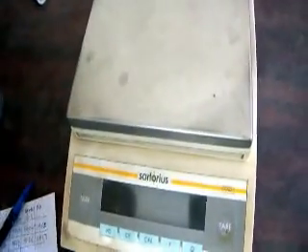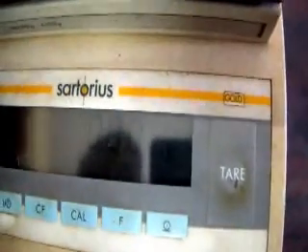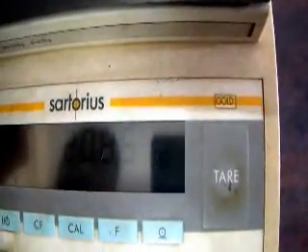Now this is the third, for the 30 centimeter soil sample, and this is 00. So this is 20.85 gram. So this is the gravimetric sampling method. We need to take the weight of wet soil plus box, weight of dry soil plus box, and weight of the soil sample box to find out the soil moisture in terms of volumetric content in the soil.